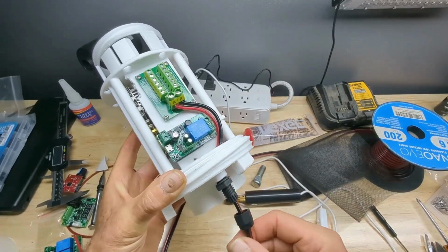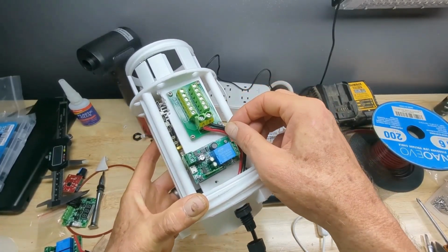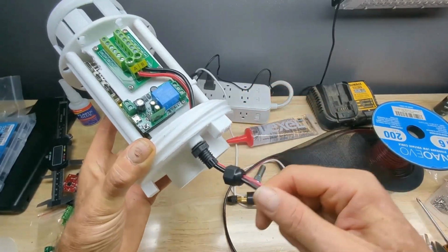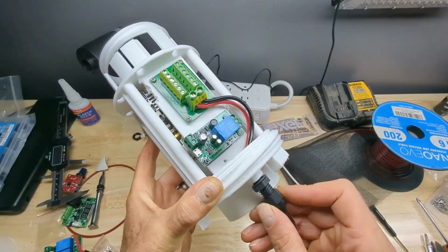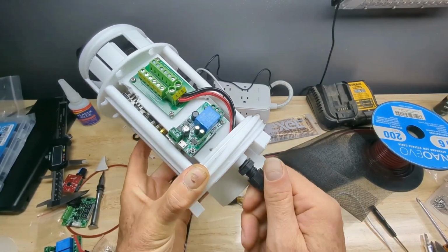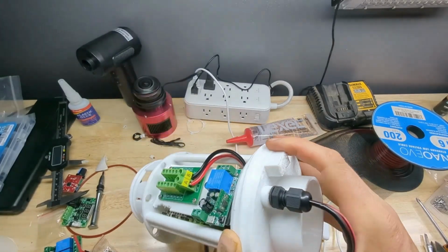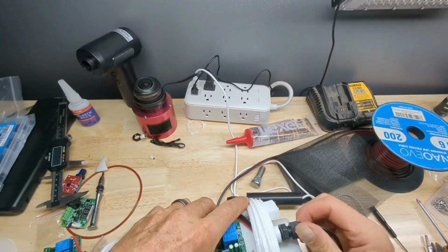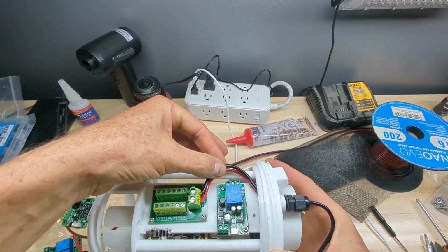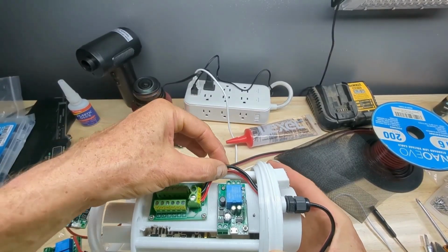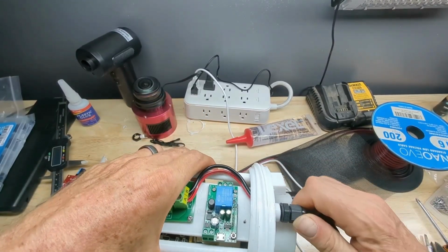And you don't want to have any kind of situation where these things could get loose, because this cable is continuously being yanked when it's not secured. So just push that up on there and tighten it up. As you tighten, it will tighten those fingers down, and you'll see you have already a little slack left in here just in case, a little stress relief on the cables. But once you tighten this up,